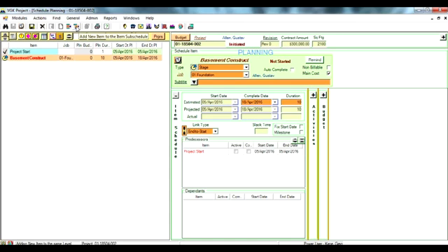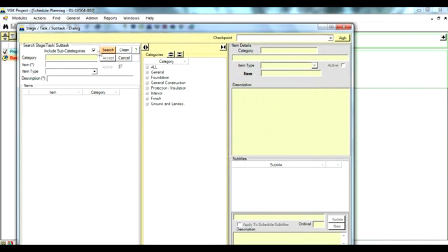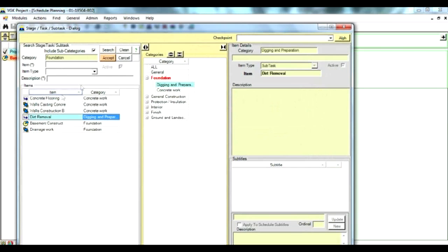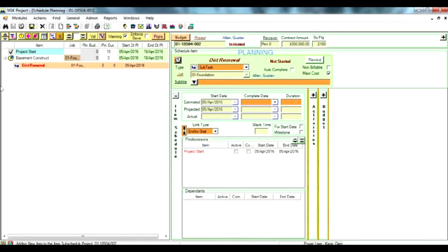So with the next item, we want to add some more details to the basement construction section. To do this, use the toolbar button, Add New Item to Item Sub-Schedule. This will create a new item and place it into the sub-schedule of the basement construction. Notice that basement construction was sub-scheduled and dirt removal was added as the first item within it. Project Start was used as a predecessor, and a default link type is given, which you can change to suit your needs. The job link was also inherited from the parent item, basement construction. So we just need to specify duration for the item to be successfully added to the schedule.